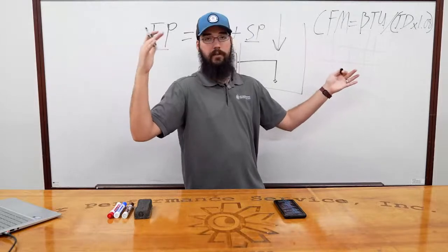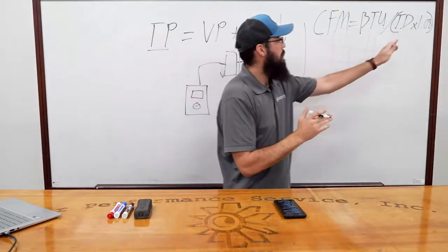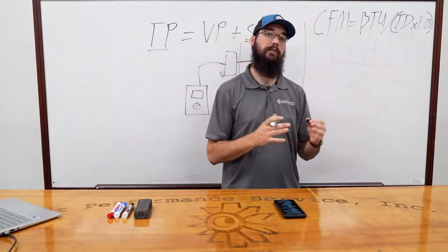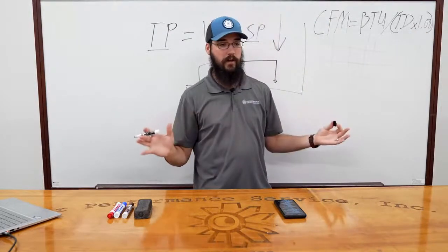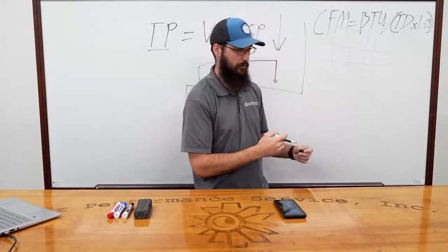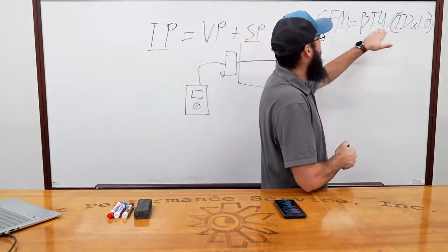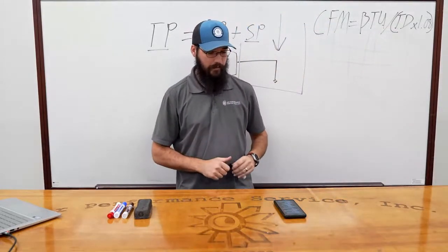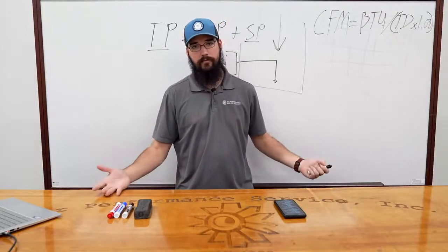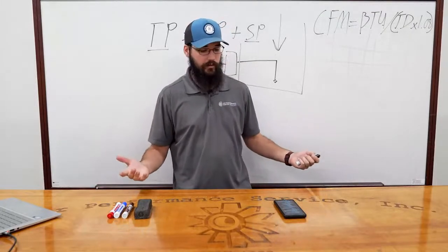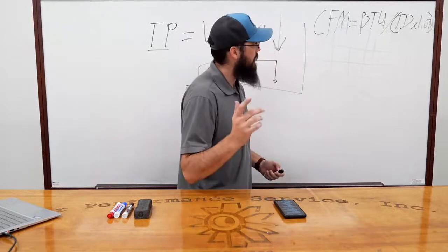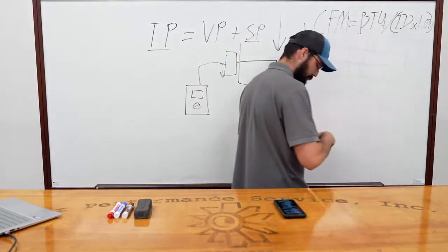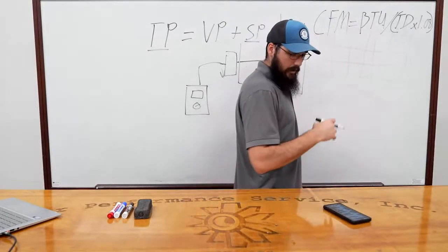You've got your supply temp and your return temp. Take the difference and multiply that by what's known as a coefficient. So 1.08 is the coefficient for the formula. It doesn't matter what a coefficient is, that's just the number you use. Then you divide that into your BTUs. That's grand, fine, awesome, but I've got electric heaters. What BTUs does that mean? That's okay. Furnaces have BTUs listed on them if you're not familiar with that. I'm pretty sure most of you should be.